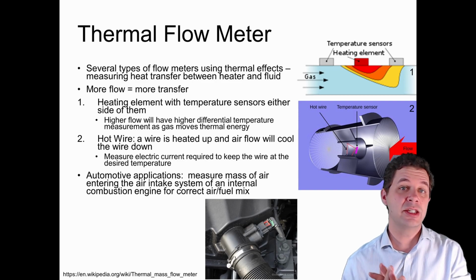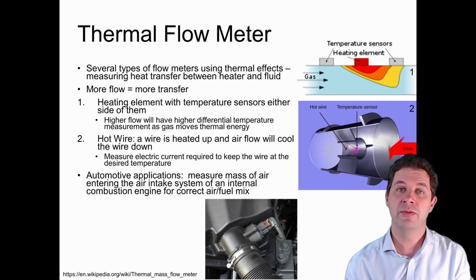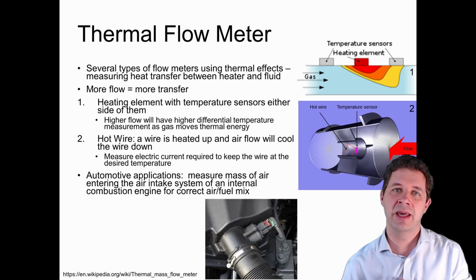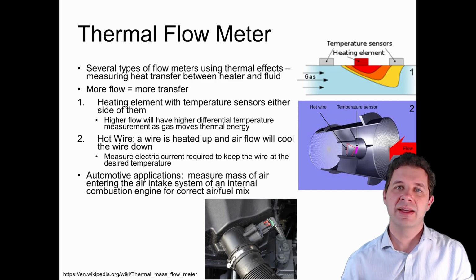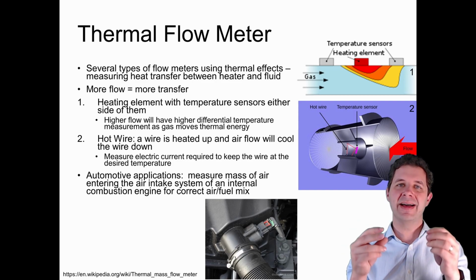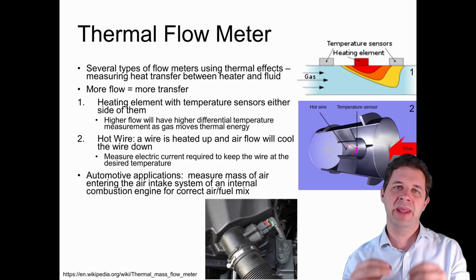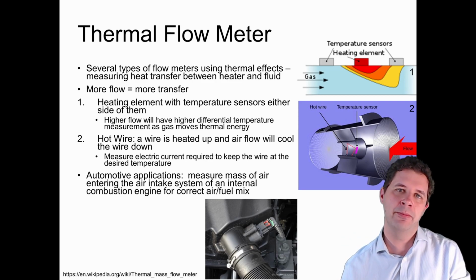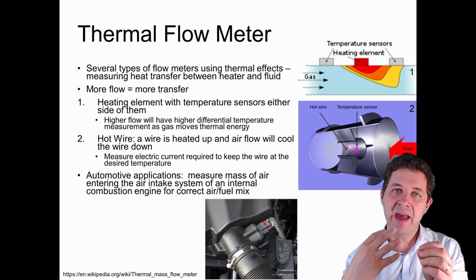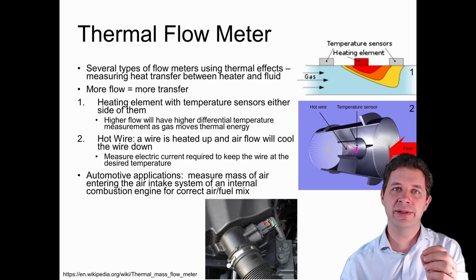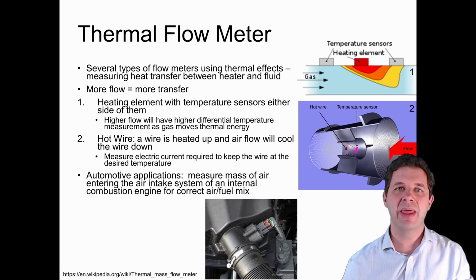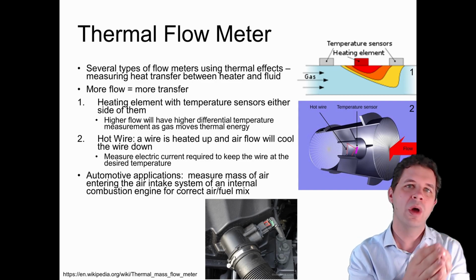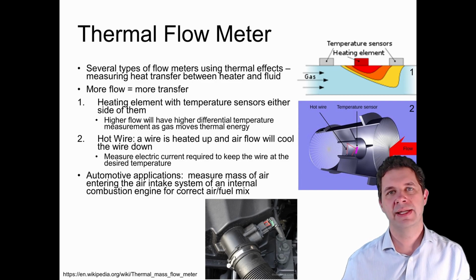And essentially, these are often used for internal combustion engine vehicles to measure how much airflow they're coming into their air intake. And in doing so, essentially, we can have a whole lot of air rushing past a wire that we're heating up. Now, the way we heat it up, we put a current through it, and we try and maintain it at a particular temperature. Now, as we have more airflow blowing on it, it's the equivalent of you've probably had some hot food at some point and you blow on it to try and cool it down. The more you blow on it, the more you cool it down.